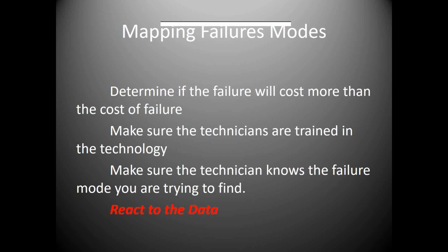A few years ago, I used to tell people don't buy the MCE, the motor circuit evaluation testing tools, unless you've got an electrician there who knows how to read the data. Well, now these companies do the training online. You send the results to them. Anybody can go out and take the readings. They tell you what's wrong with your electric motors. They tell you what's wrong with your switchgear. Make sure the technician using the tools knows what they're looking for. And again, the key thing down here in the red: react to the data. If that data tells you you've got a coupling misaligned, align that coupling.